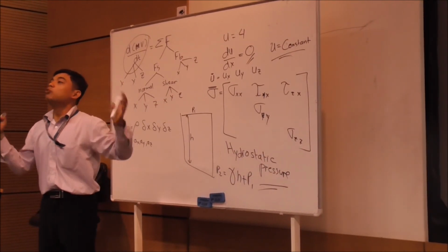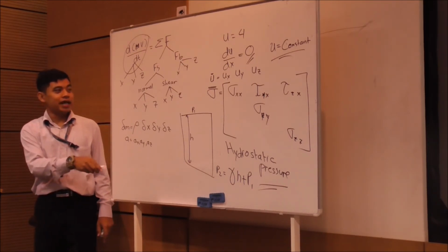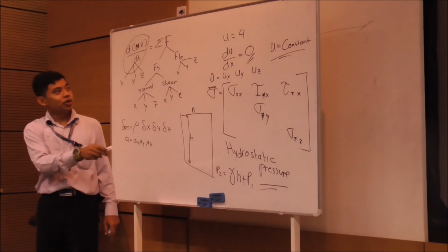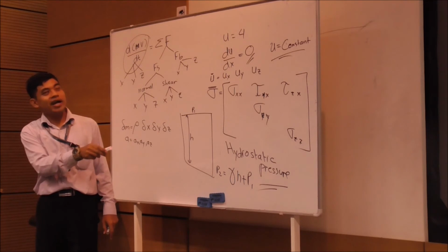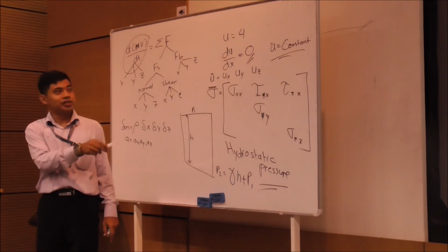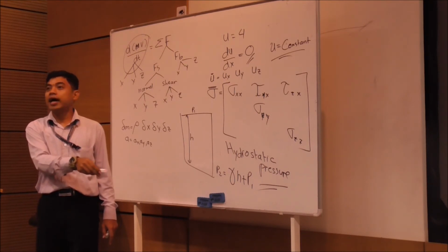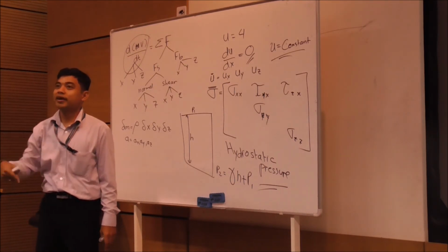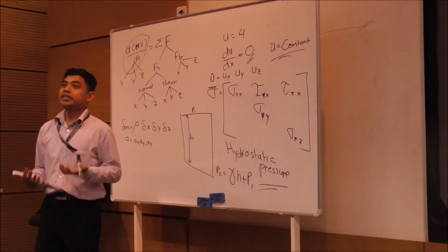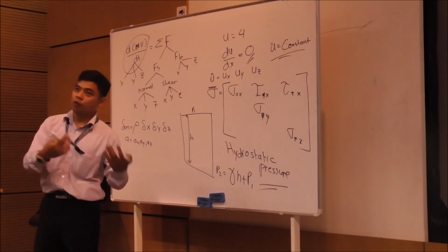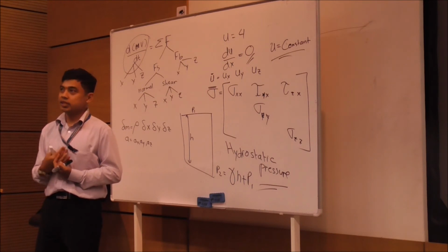If the fluid is not moving, this one becomes 0. So you will know that only this one is there, because then dp/dx is equal to 0, dp/dz is equal to 0. So the only pressure working is the hydrostatic pressure working in the y direction. So now you know that Navier-Stokes is very powerful. It can be used for both fluid flowing and fluid at static condition.